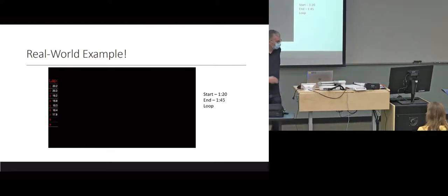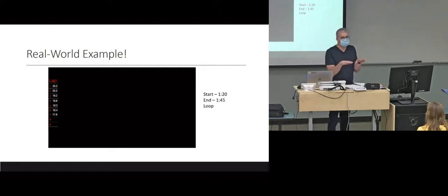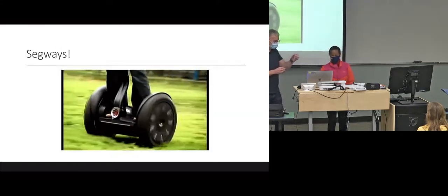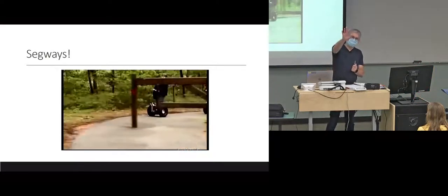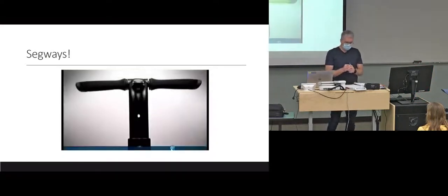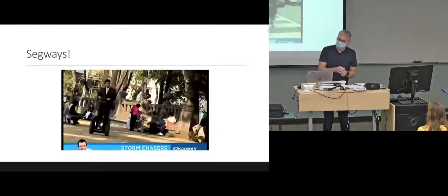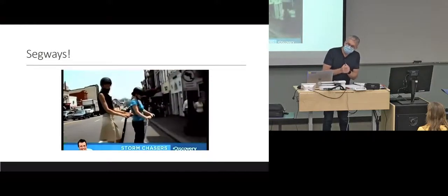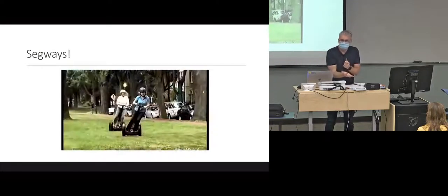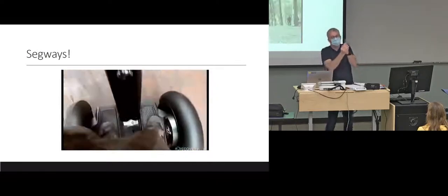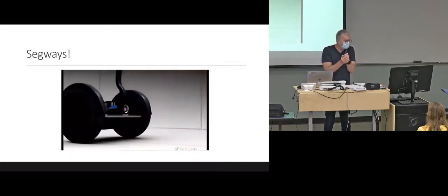Okay, so just a little bit more about the Segway. Why is it that when you lean forward, you accelerate? So I know the camera is very far away and it's getting ready to turn off, etc. But the thing you need to think about is the wheels are in the cart that's under your feet. If you're leaning forward, the only way to prevent you from doing a face plant is if the cart moves under you to try to catch up with you. And if it accelerates fast enough, it will invert the pendulum and stand it up. That's how it works, okay?